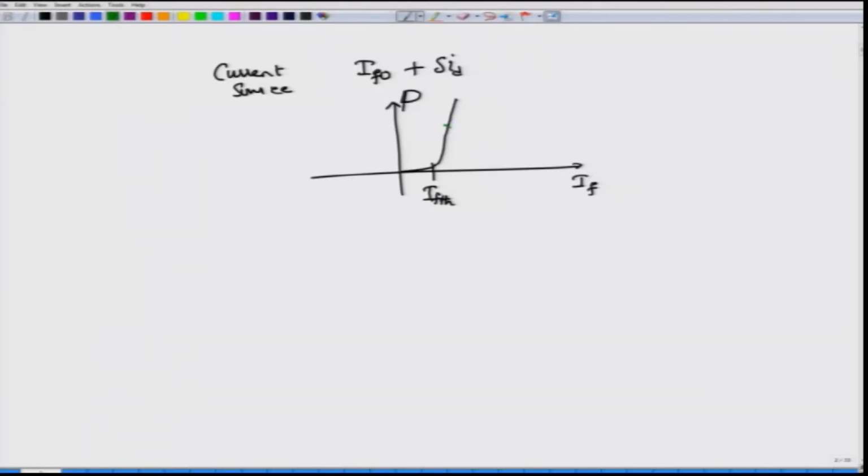Usually you have a sort of current limiting mechanism in your circuit in the form of a laser driver. But nevertheless, your laser driver will usually operate at a certain operating current. So, IF0 would be the operating current. Now, if you want to modulate data, which I will assume would look like this in the form of a simple sinusoidal signal, this is the modulating signal or the data signal out here.